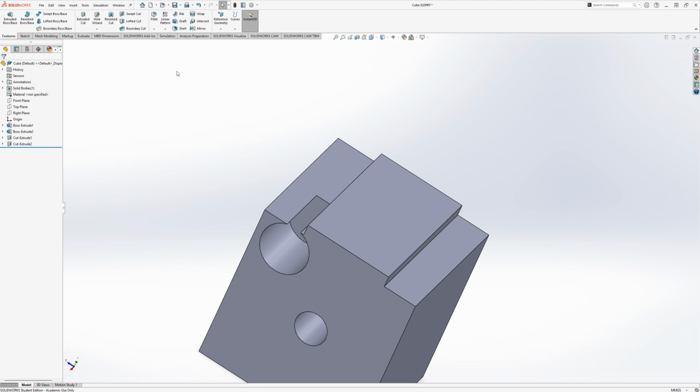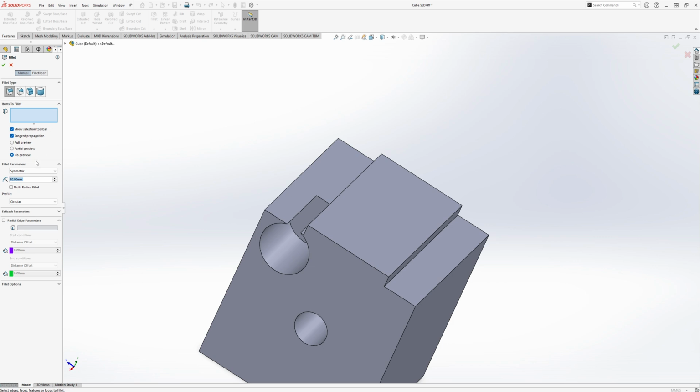This has many uses. Usually I personally like to use a chamfer for something I want to look aesthetically nice, whereas a fillet may be something that I want to have a friction fit in, especially for 3D printing. Fillet is very useful because it rounds off the edges and it allows everything to fit nicely in. So exploring fillet first, all we're going to do is go on fillet. Now depending on the graphics card that you have on your computer, you can choose one of three options. Because I have a 4070, I will be clicking the full preview.